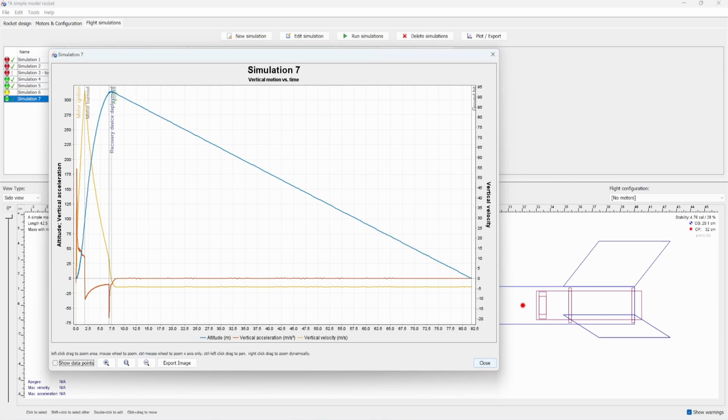Okay, now we move on to vertical acceleration. Keep in mind that this is not speed, rather acceleration. We can see here that the engine ignited and the engine was burning in full force and it went down, and then the engine stopped burning. With this very low spike, we can see that this was a deceleration from the ejection charge. From there on, it should be zero acceleration, as the parachute is dragging it down and there's nothing else pushing it. Now we move on to vertical velocity.